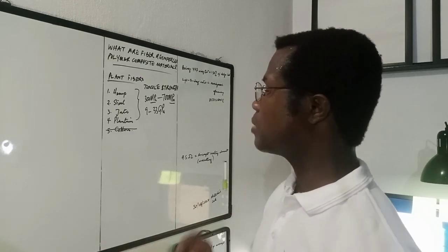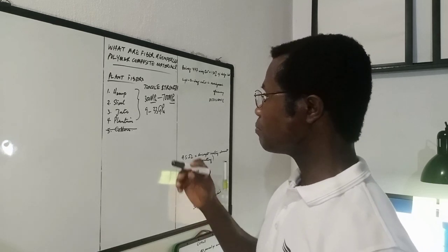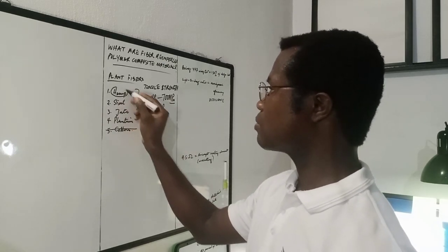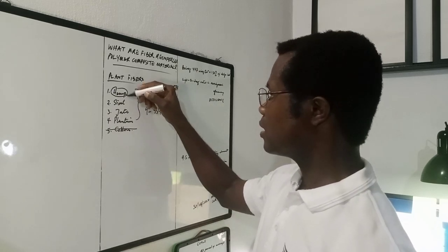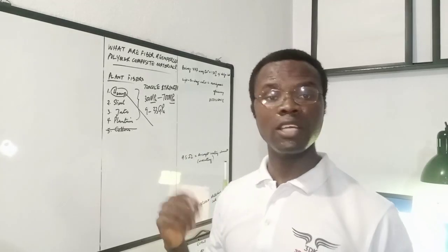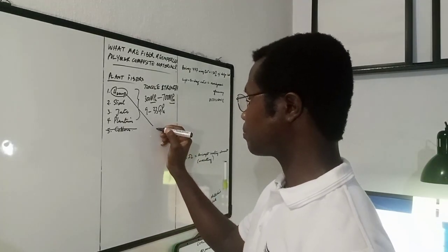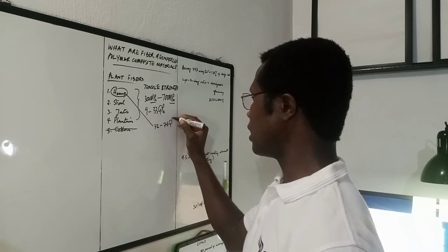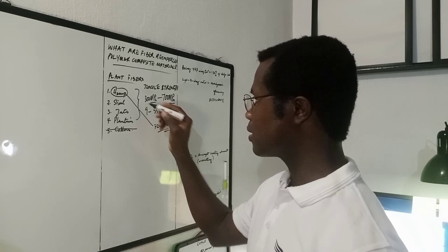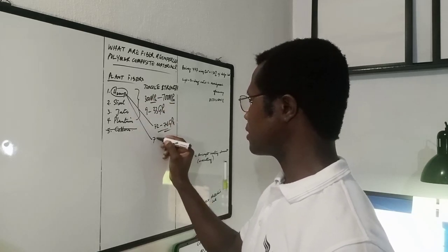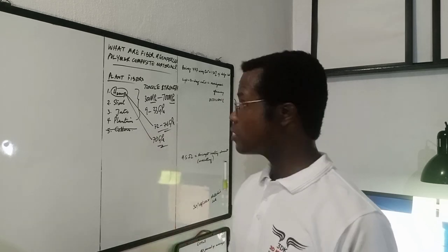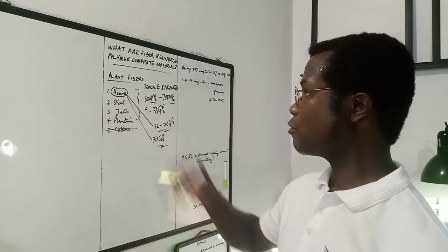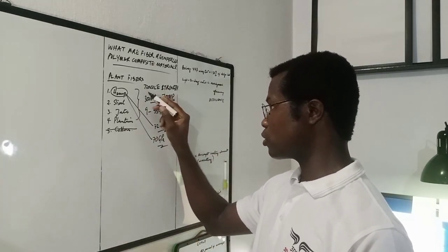But with these natural fibers, one other important thing to note is that even though you have these numbers, there's a small exception to the rule with hemp in terms of the elastic modulus, that its elastic modulus is very comparable to that of E-glass. E-glass has an elastic modulus of 72 to 76 GPa, but hemp comes very close at 70 gigapascals. So this is one little exception to that general rule that the properties don't quite match up. But on the tensile strength front, it does fall within this range. So that's also a limiting factor.